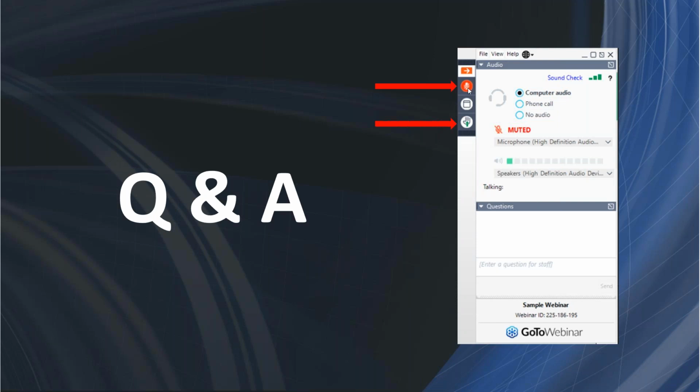You're welcome. I have one question about gate locations and gate sequencing. My experience is based on a few large Moldflow exercises we have been working on for some part design, and there's a lot of hit and trial method. The Moldflow experts do it this way, and sometimes they were surprised. We have a big pressure drop and tonnage drop. When we start working, maybe after 20 attempts, we get a very good drop. I'm very surprised: same gate locations, but different sequences.